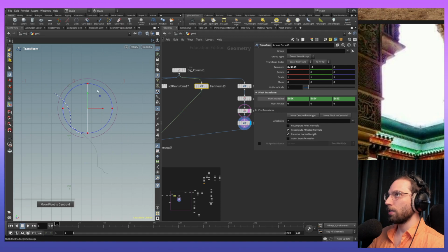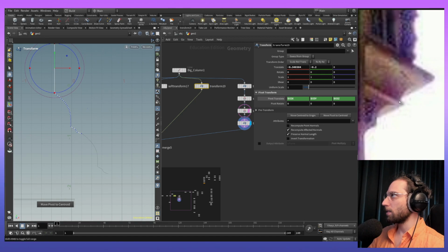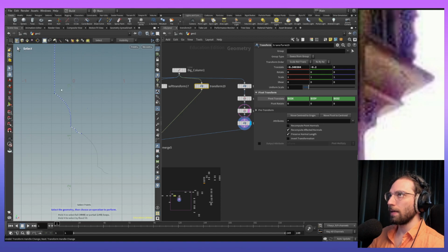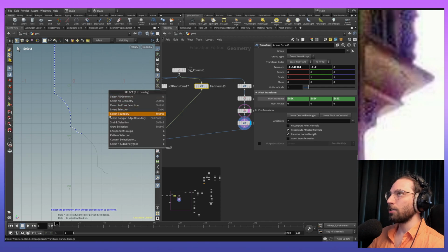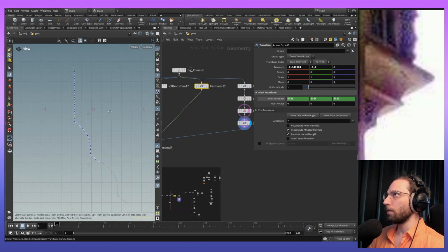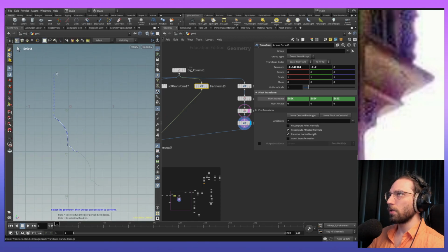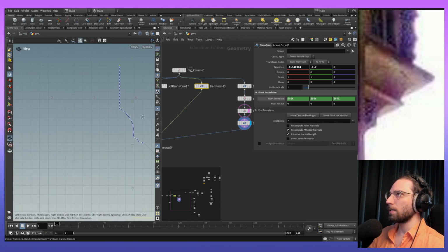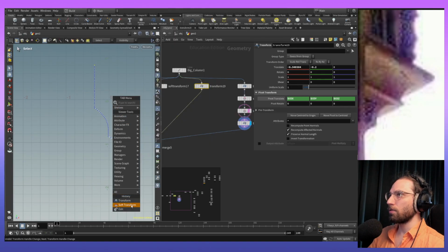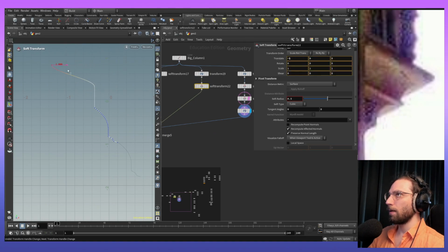And let's actually transform it where we want it, right? And this way we will have it where we want it, right there. This is looking good. I can see that this pump here has quite the aggressive angle, so we will work with that now. We will press 2. That's amazing. We'll pick a point right there. And actually, let's try to work macro to micro here. So the first soft transform I want to do is this thing here. So let's click the last point and add a soft transform, and then take that bad puppy right there.